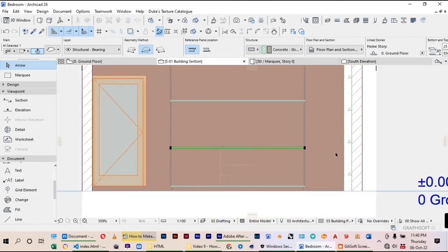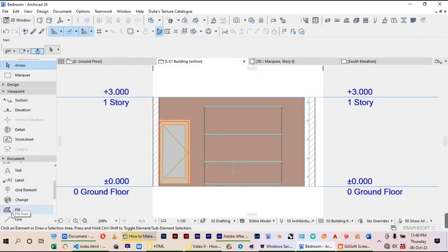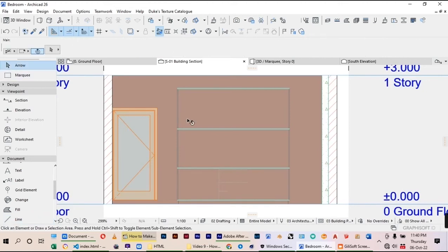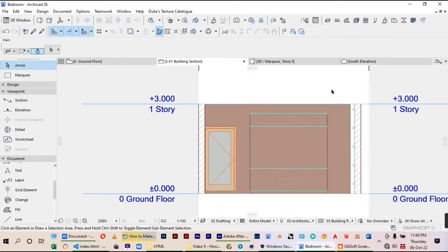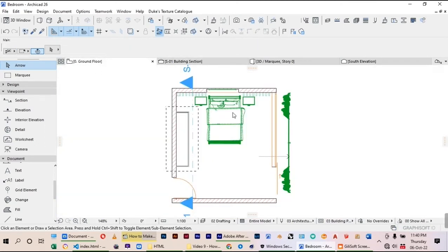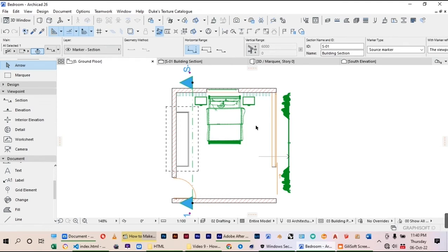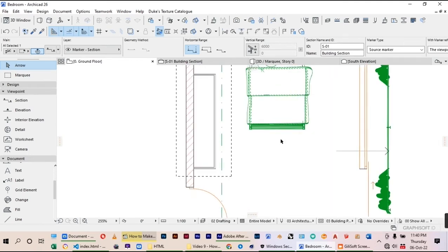And then the other shelf should be at the height of the door. The other height should be at there. So all we are left with is to fill these spaces with doors and drawers. Now I'll use the profiler to create the doors as well as the drawers.